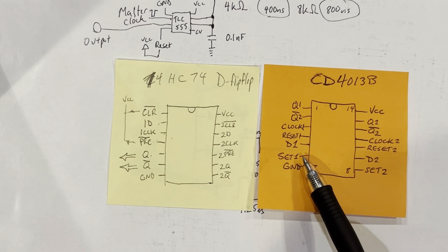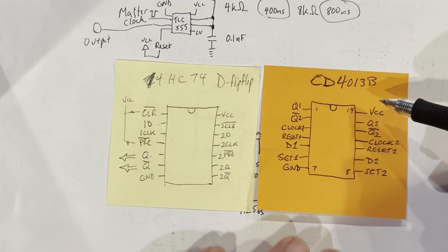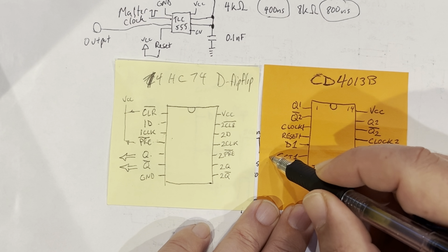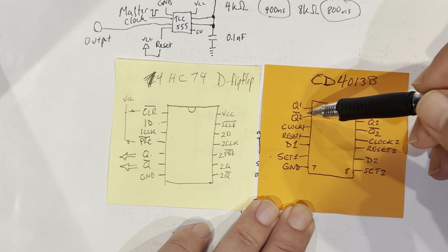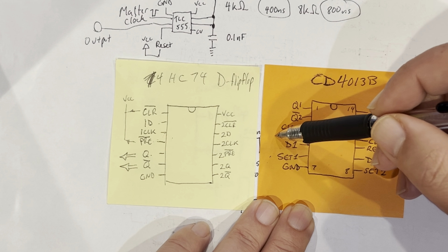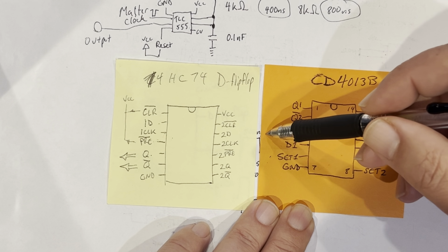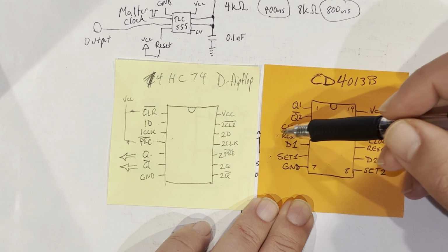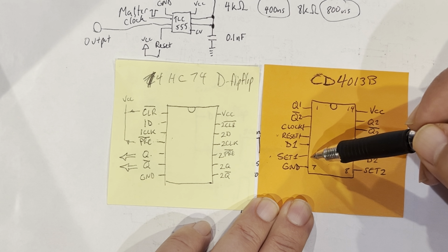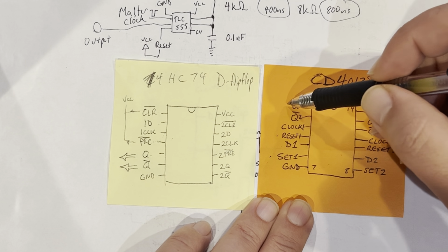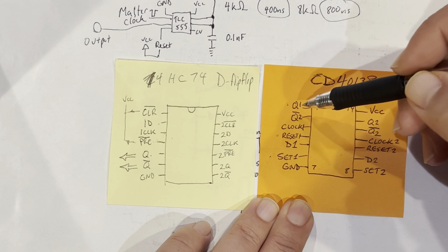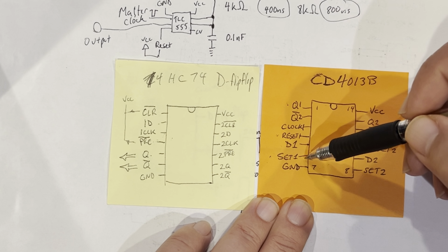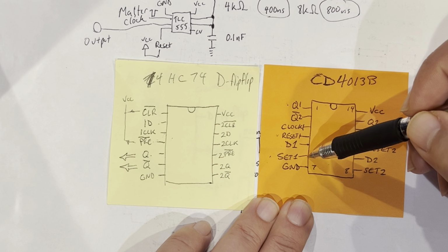So I'm thinking to myself, well, if I could get a pulse to go into set, and then I have the reset tied to high so that it's set. After the propagation delay happens and the reset actually turns it down, if I measure the output at Q1, that will give me a high pulse, because it'll be at least 300 nanoseconds to get this to go on.